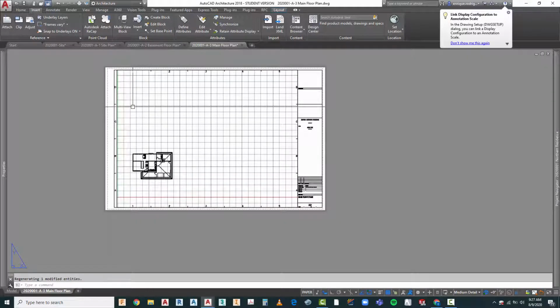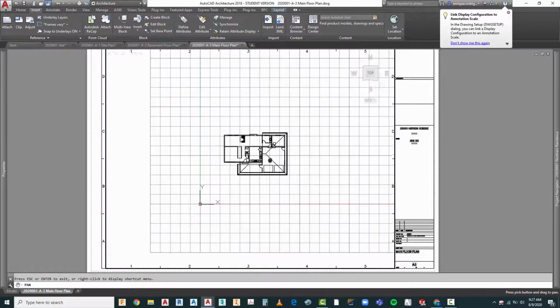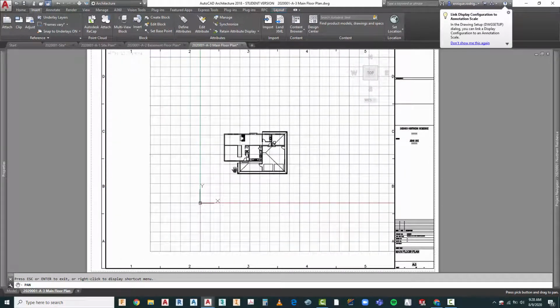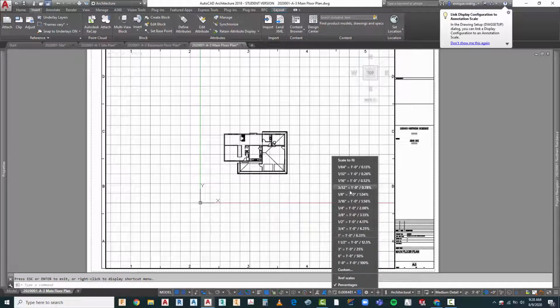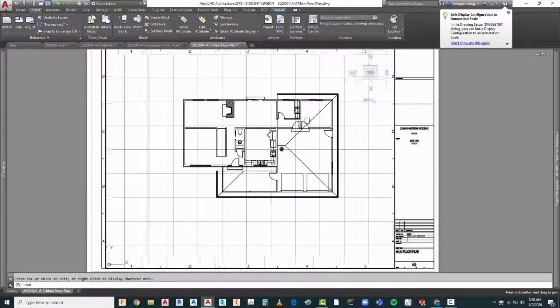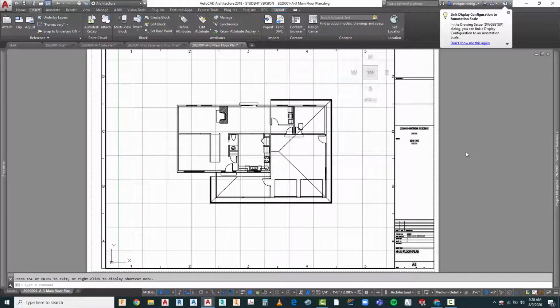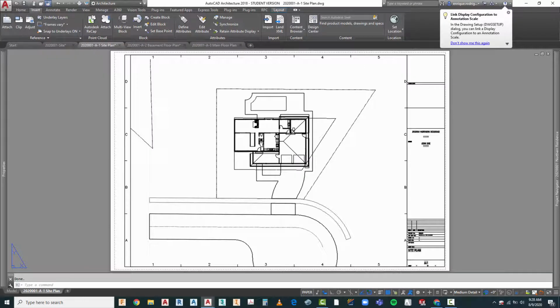Let's go back to our paper space, open up the viewport, and pan this towards the middle. Now the reason I pan it towards the middle is when I change my scale, sometimes if it's off to the side, it'll disappear off of my viewport window. So by centering it, I'm sort of stopping that from happening. Okay, there, that fell right into the middle right there. I'm going to just slightly adjust it, close my viewport, and I should be saving these as I go along. So I'm just going to go back to each one of these and save them.